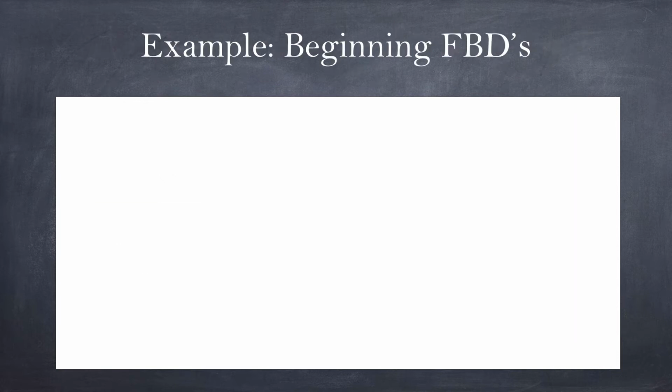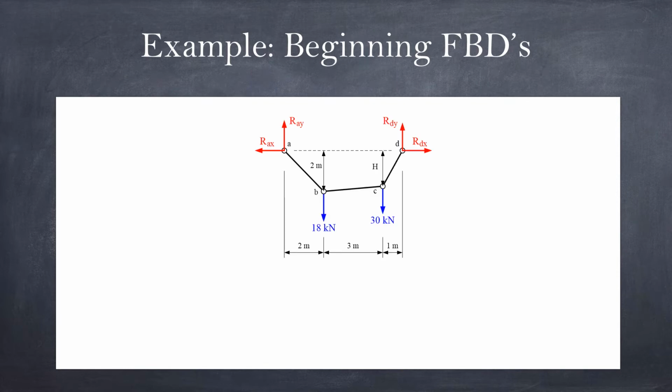Well, let's look at the free body diagram, because our problem doesn't end just because we have enough equations. This is a more complex situation. If we draw the whole free body diagram from A to D, then we will have 4 unknowns. This is a body, so we have summation of forces in the x and y directions and summation of moment, so 3 equations. We have 4 unknowns and 3 equations. Obviously, we cannot solve all 4 forces using one free body diagram. There are many ways to do it. I would choose the one that is easiest to explain.